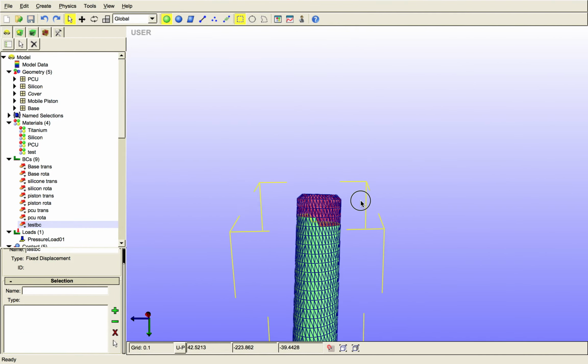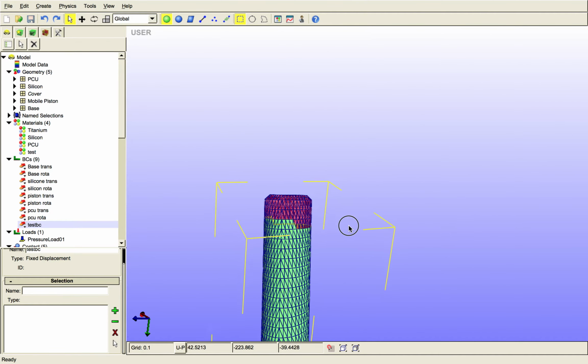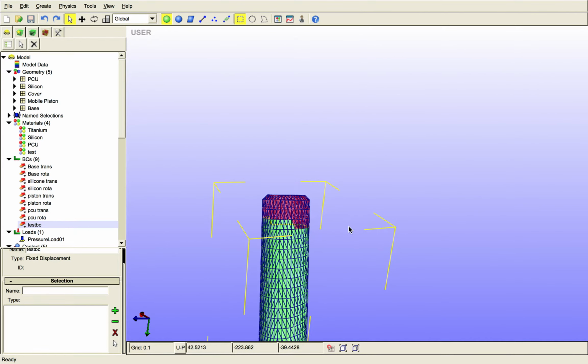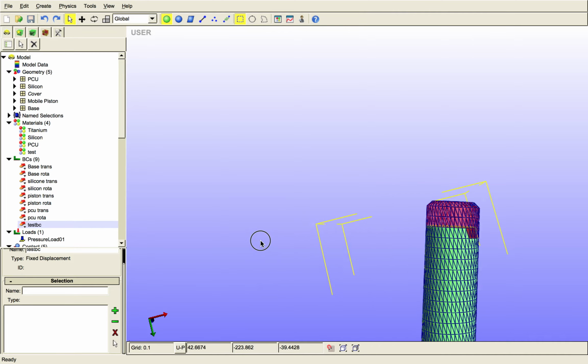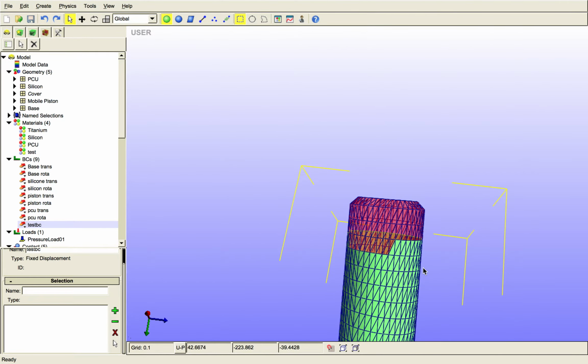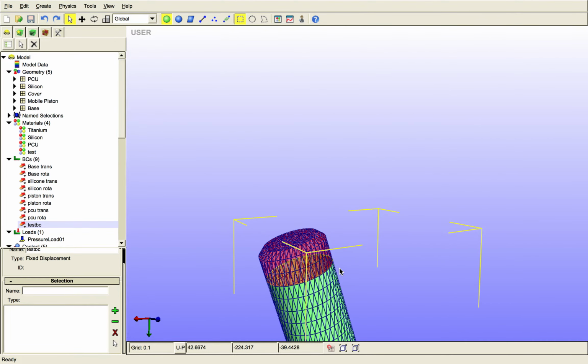As you can see, I have some more elements that I want to get rid of. You can unselect them using control and drag again, and repeat the operation, and it's perfect. Now just click on the plus button and all the numbers of the elements selected have been added to this section.